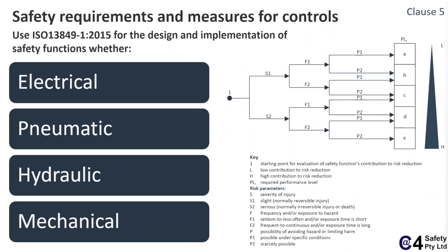This is something that has to be debated in the subcommittee that's looking at these, and this is where we want the experts to come in and help us as to what they think. But ultimately, in Australia, you must, according to law, perform a risk assessment and go so far as is reasonably practicable. And the first two tests in reasonable practicability are severity and probability, which is your risk estimation. So you've got to conform with that and put your control system in accordingly. So if you come up with PLE and the standard says PLC, well, you've got to go PLE. End of story.